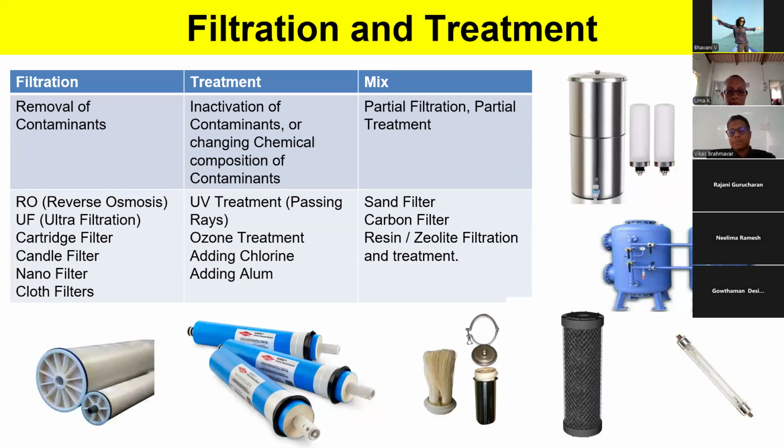What is treatment? Treatment is, say you take a sample of water, you add a few drops of chlorine or you add alum to settle it, right? So you're not physically removing anything from the water. You're doing some treatment for contaminants to either settle down or react in a way where it is not harmful, right? So this is a significant difference. So if a purifier guy comes and says that I'm giving you an activated carbon filter and a UV filter, then it is not a filter, you're just doing a treatment. So you should be aware that you're not removing anything from the system. You're just doing some treatment.